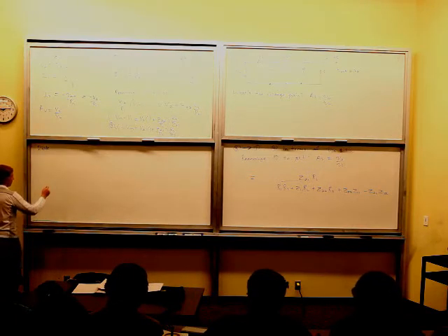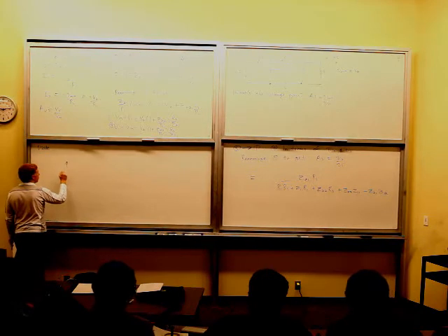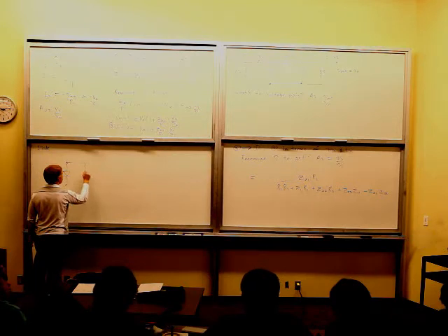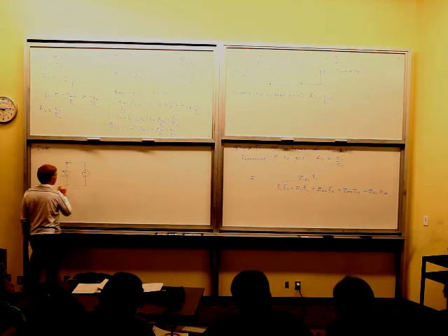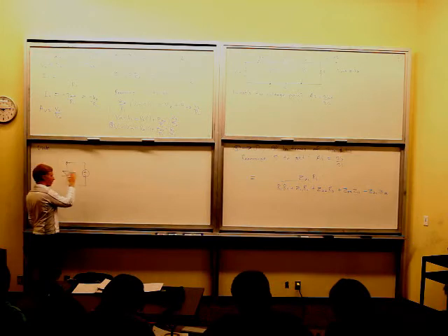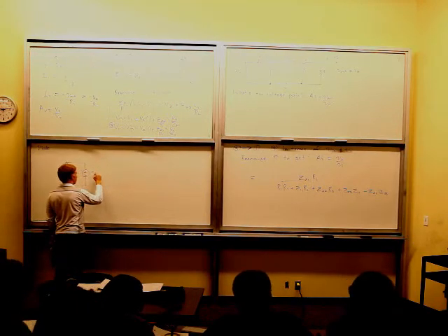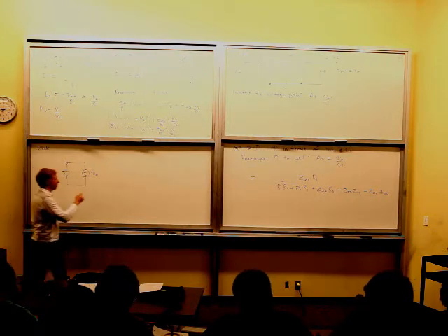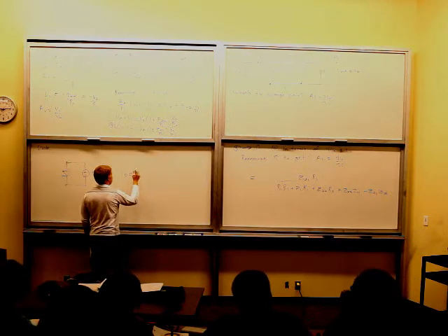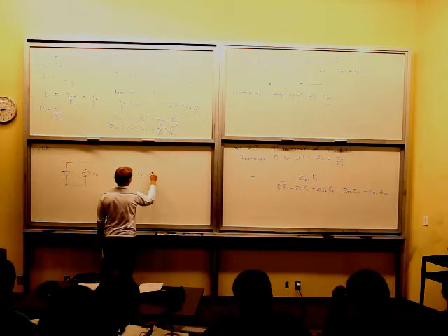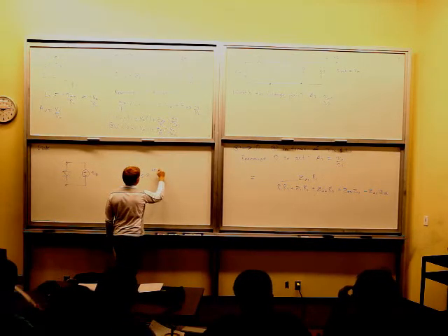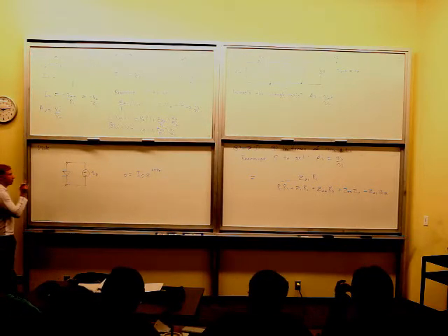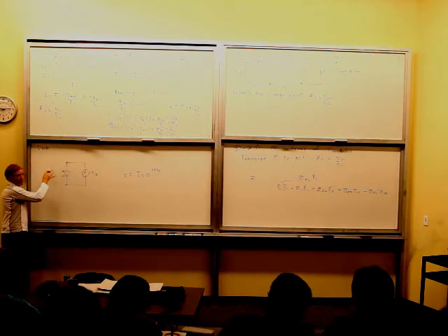Generally, if I just have a diode connected up to a voltage source, so here I connect it up to some very specific voltage, and there's no other resistances here, I really then care about that exponential relationship. Then I really care that ID equals IS e to the VD over VT. That's my approximation equation. If I have a voltage directly applied to that diode, then I really care.